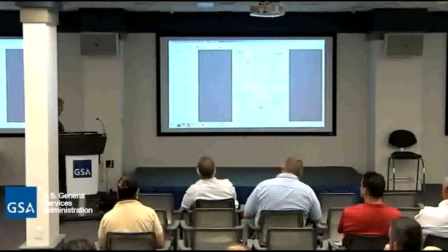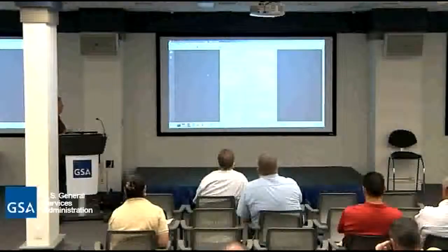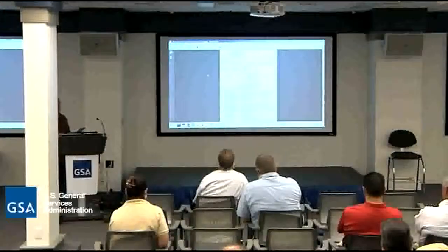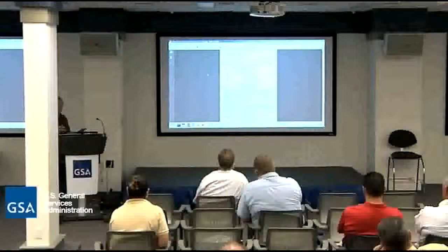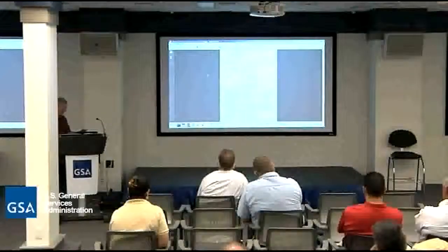Indoor water line break. Okay. If you are going into a building, or even this is predominantly inside buildings, and you observe a leak on it, your first step should be contact the building manager or call the mega center to report the leak. This will get a team out, whether it may be your own personnel or GSA's O&M contractor. Go out, turn off the water, stop the leak, and assess the situation.